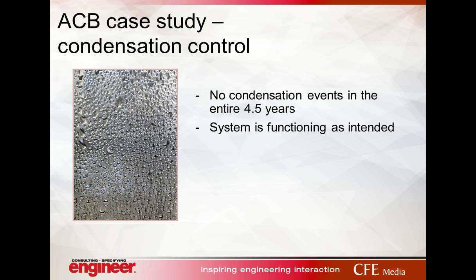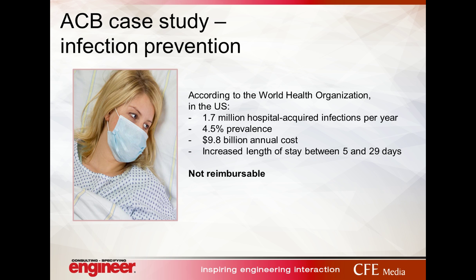never approach it. So in 4.5 years or so of operation, there's been one instance of condensation, and that was when there was a failure in a sensor in the secondary chilled water system that caused us to send too cold water out there. That was diagnosed pretty quickly and solved. So with the exception of that one event, there's been no condensation in these rooms. As long as your envelope is tight and no outside air gets into your rooms, the surface temperature of a chilled beam is actually warmer than that of a VAV diffuser. So the VAV diffuser is more likely to condense.